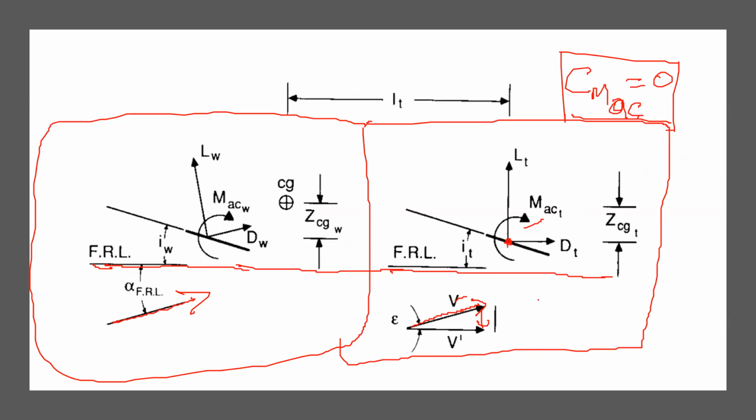So see that in our computations, while deriving the stability conditions, we are assuming that the airfoil is symmetrical, and the question which was asked in the previous assignment was from here, because it is expected that you are studying from these books, and when you do stability analysis, you take the airfoil as symmetric. And I was talking about this number LT. This number LT is the distance between CG and the aerodynamic center of the tail.